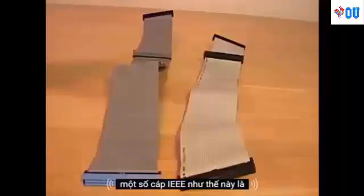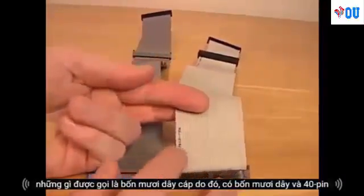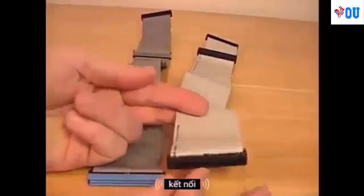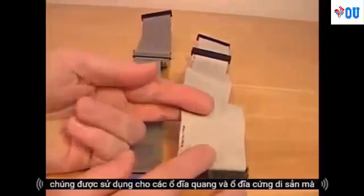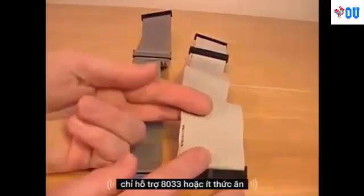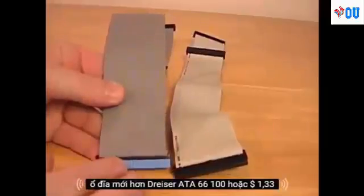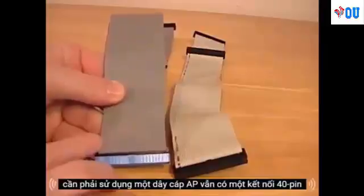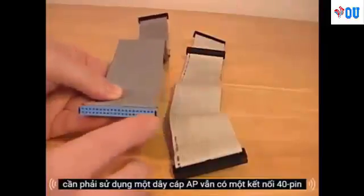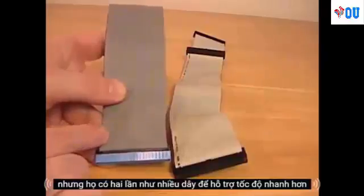Some IDE cables, like this one, are what are called 40-wire cables. So there's 40 wires and a 40-pin connector. These are used for optical drives and legacy hard drives that only support ATA33 or less speeds. Newer drives that are ATA 66, 100, or 133 need to use an 80-wire cable. These still have a 40-pin connector, but they have twice as many wires to support faster speeds.